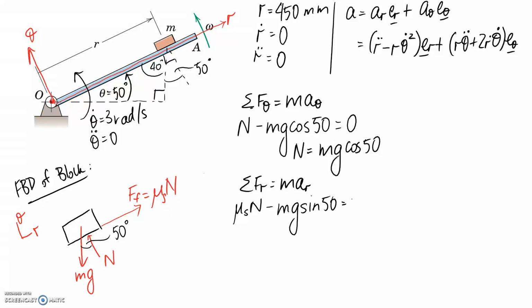On the right hand side this time we are going to have some acceleration, in that we know it's going to be going potentially down the ramp. So we can substitute in our equation, which is this part here, from our expression for acceleration in the r direction. So it's going to be r double dot minus r theta dot squared, and we've already taken care of the signs in the things that we're going to substitute in. That's why I've just substituted it in as positive, because it's a general form from the equation.